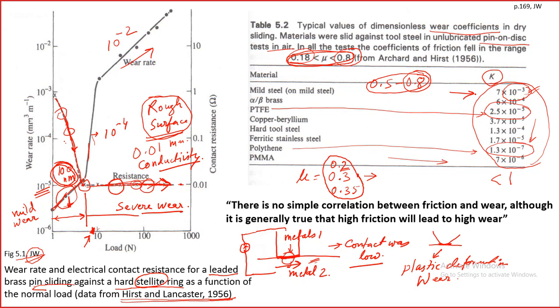And that also indicates that wear is very high. So whenever you are combining two materials together, never select same material. It will happen for all materials like brass on brass, or even for polymers, polyethylene on polyethylene. So always select two different materials, and obviously we went through all the solubility rules and so on to select the best material combination.